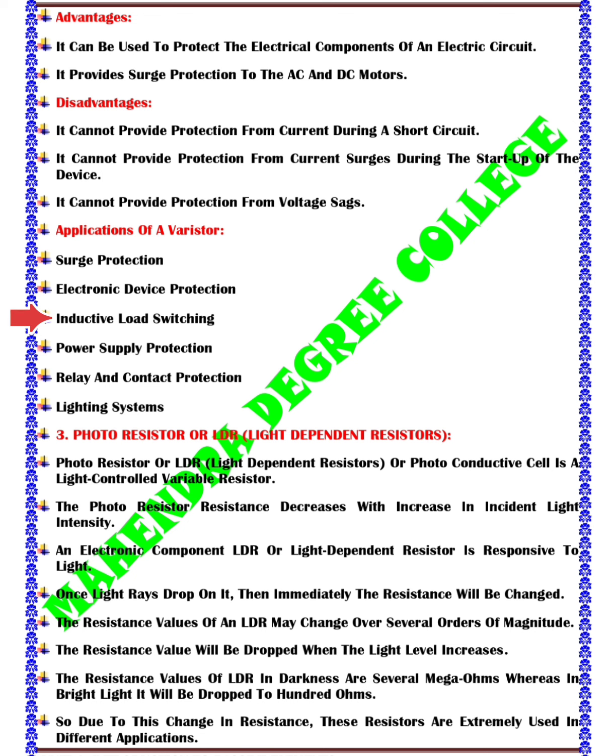Third one, inductive load switching. It means, when devices with coils, motors, transformers, and relays are turned off, they can generate high voltage back EMF. Varistors absorb this energy, protecting switches and semiconductors from damage.